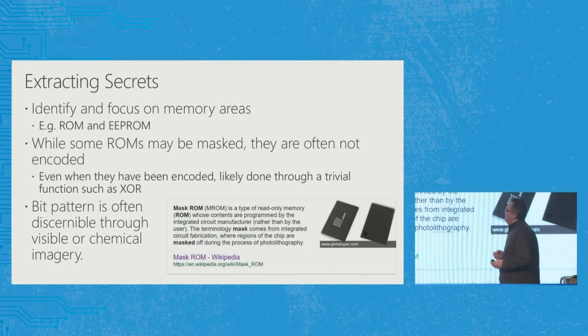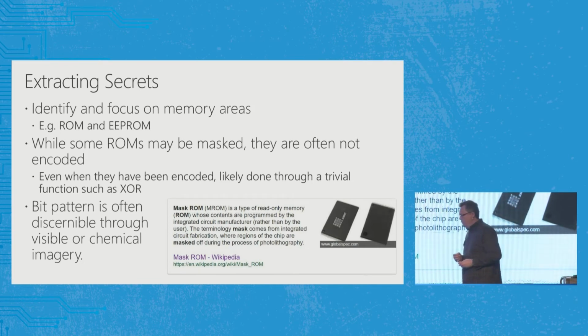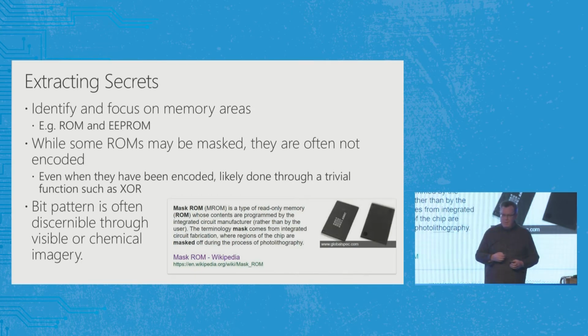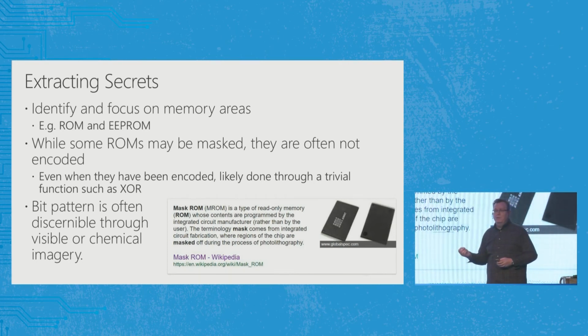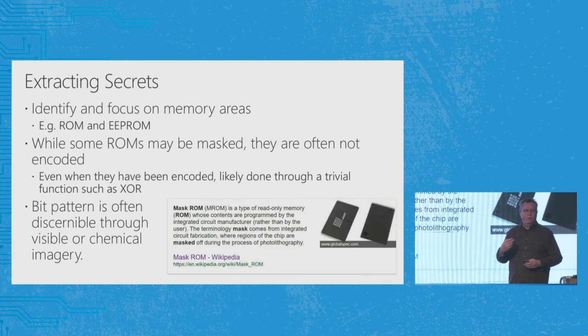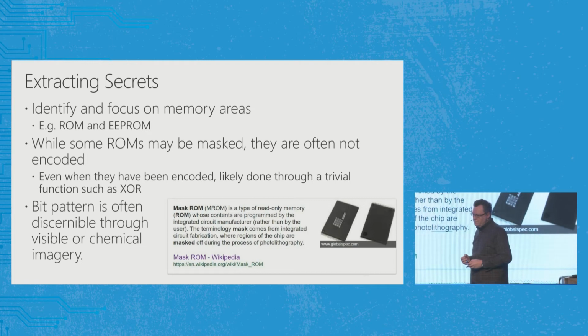So when it comes to the chips themselves, for example, when I talked a little bit about helping MAME recover the code on mask ROMs, so much of the code that is physically on the chip to begin with is not encrypted. And unlucky for many of the manufacturers of the chips today, those that say that they are encrypting it are actually just XORing the code itself, right? So very easy to extract, very easy to move on.